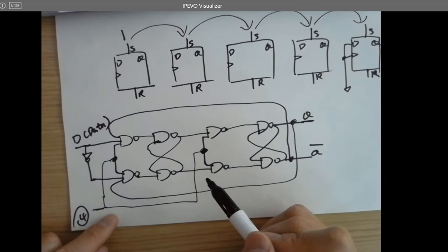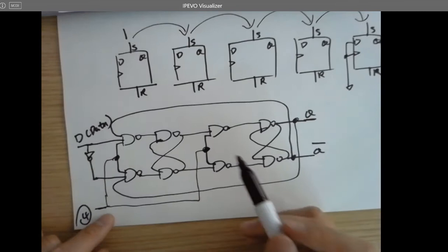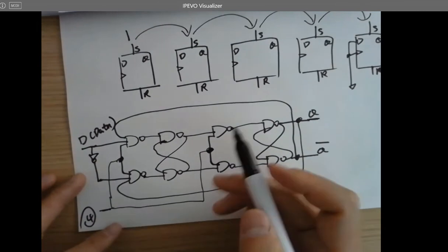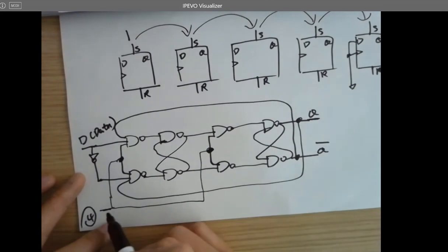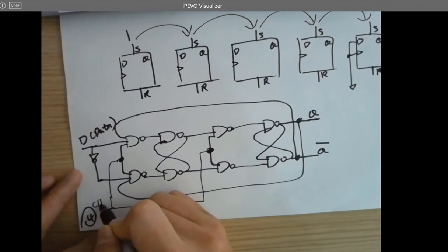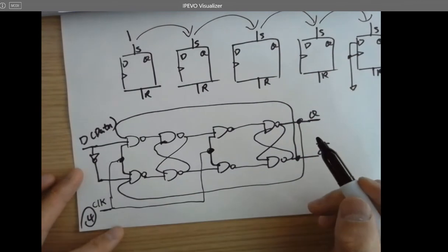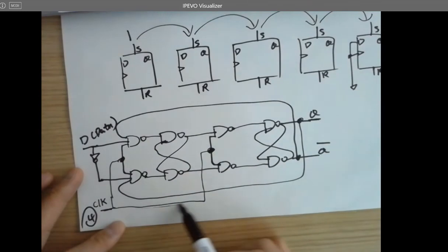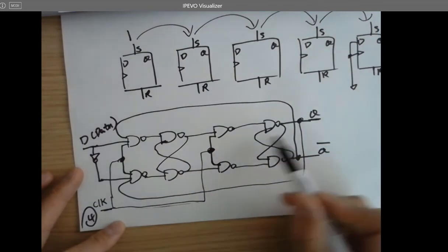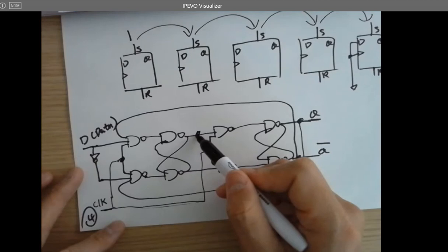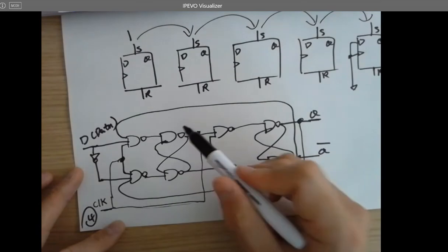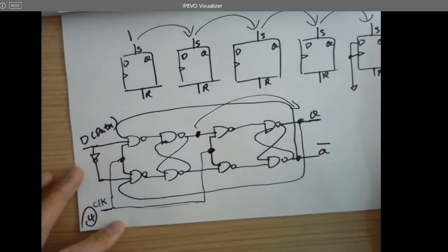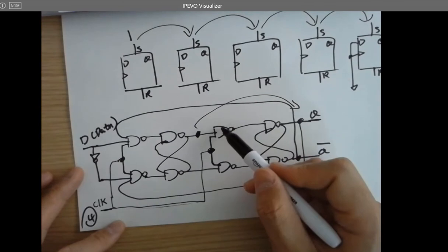So that's rising edge trigger, right? For example, here's the clock signal. Rising edge. So nothing should be put in here because you want the rising edge to send whatever is temporarily saved over here to here, because rising edge is going to enable these two NAND gates.